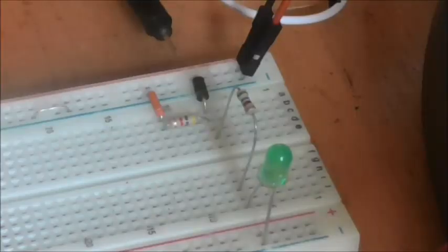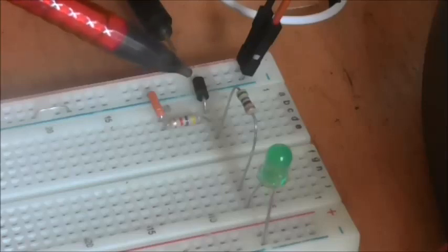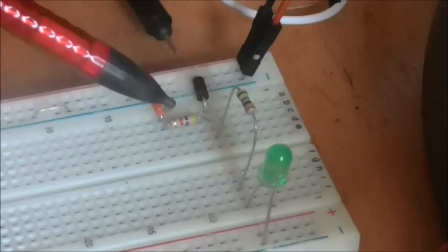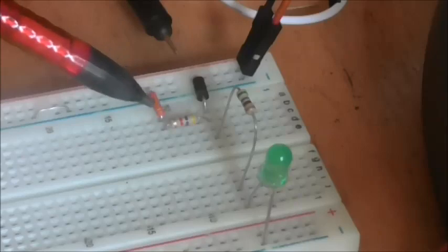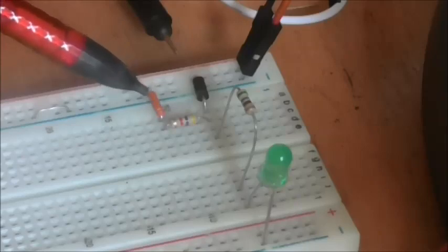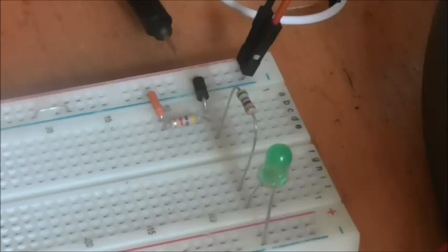So this is the circuit for our half-wave rectifier made on breadboard, and I don't think really we can grace it with the term circuit because there's not much to it. What we have is an AC power supply coming into this rail, and a diode coming out. We have a 4.7k resistor there to make a comparative load. From the end of the resistor it goes back to the supply rail, and between there and there what we should have is an AC supply modified into a sort of DC supply.